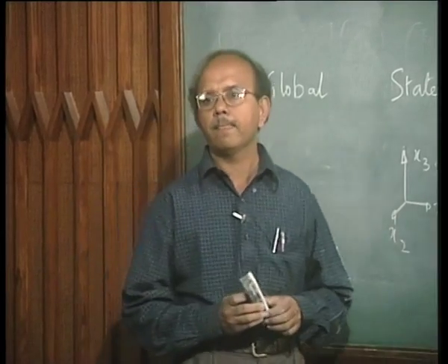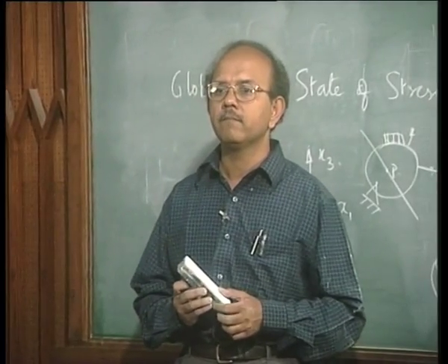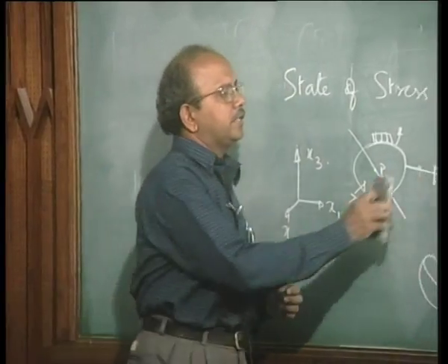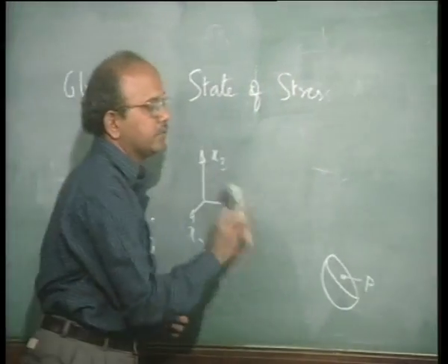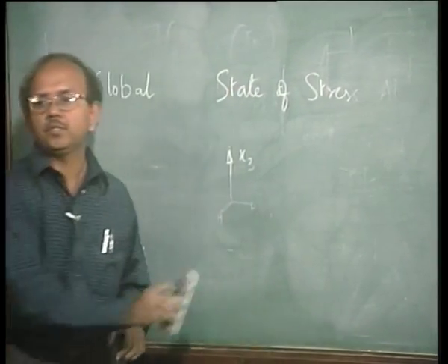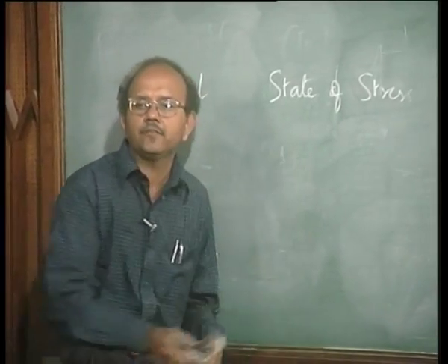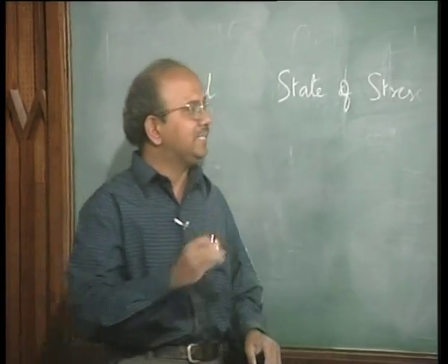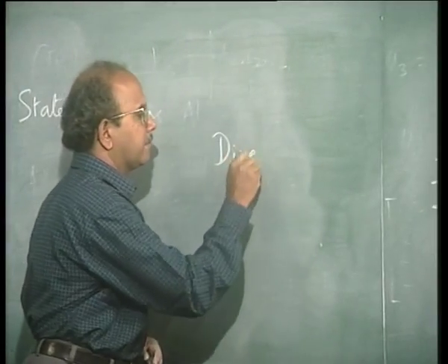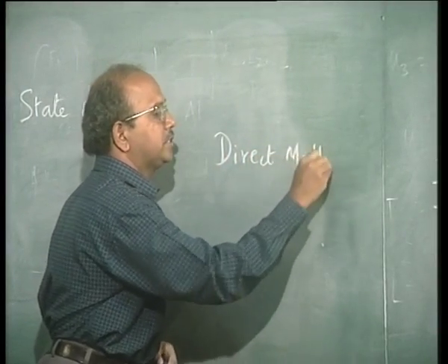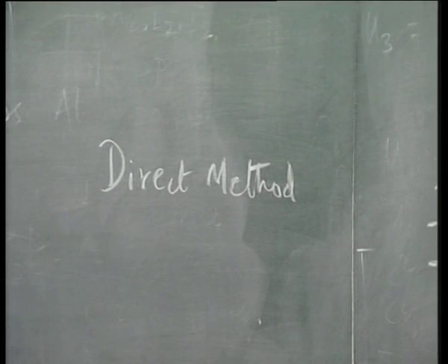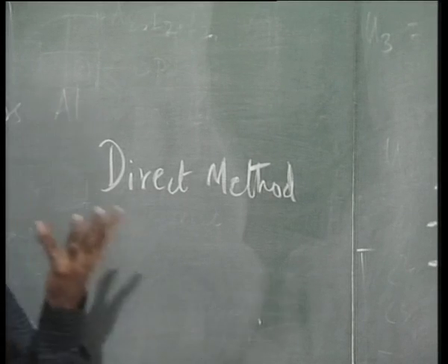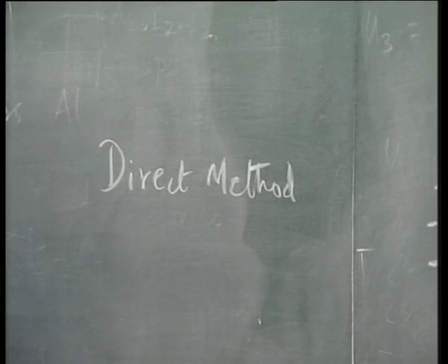Yeah. So this concept of stiffness matrix is true only for bars of constant cross-sectional area. Yeah, very good. So that's the next question. That's a very important question. It's good that we stopped here and you asked the question. The technique that we used in order to arrive at the stiffness matrix is a direct method. So the question is, is this the only way, or in other words, if I have a tapered bar, or some other shape, not going to be a bar but any other shape, how do I determine the stiffness matrix? Can I use this same approach?